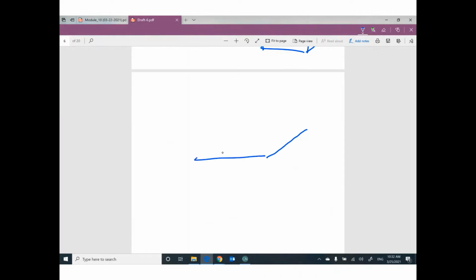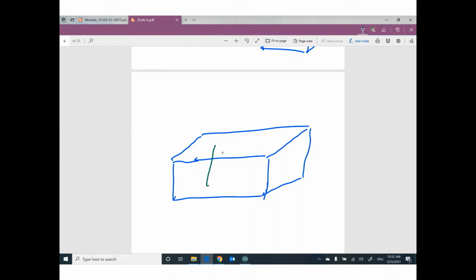Before you pour concrete, here is the formwork of the concrete footing. I will put anchors with L shape like this. And this anchors is threaded at the top. Go ahead and pour your concrete. So we are pouring concrete right now. So this anchor is fixed inside concrete. And at the top, we have something threaded.